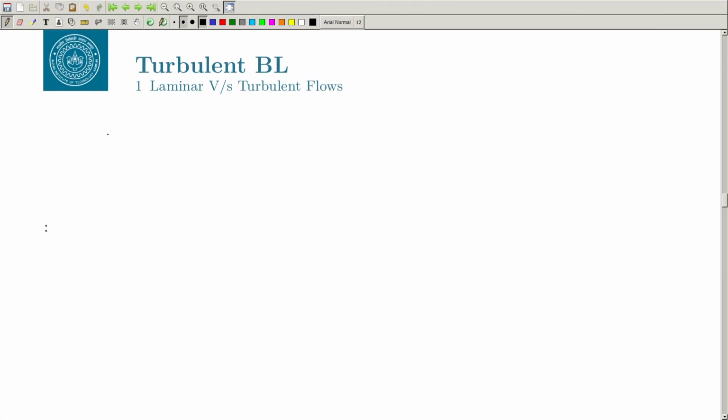In the laminar boundary layer, you can talk about, let us say, the Blasius boundary layer if there is no pressure gradient, or you can talk about the Falkner-Skan boundary layer, and you can represent the laminar boundary layer easily. For the turbulent flow case, we discussed that there are several layers. First we can broadly classify into the inner layer and the outer layer, and within the inner layer you have several layers. So let us look at those layers and how we get the laws for those layers in today's class.